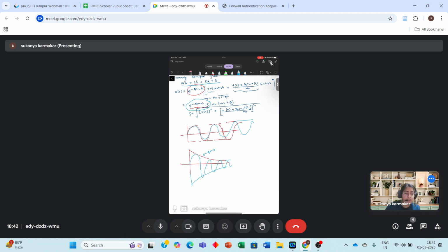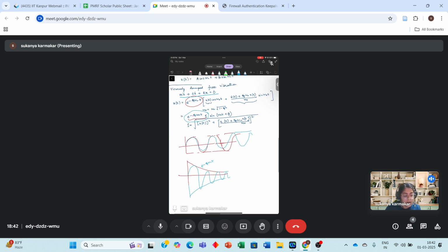The motion is dying because of damping, and damping appears in the inner part also, because here you have omega d, because of which the period of the system is also changing. But the envelope curve is basically because the motion is constrained between those two lines.